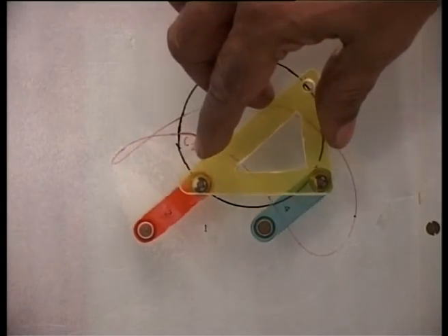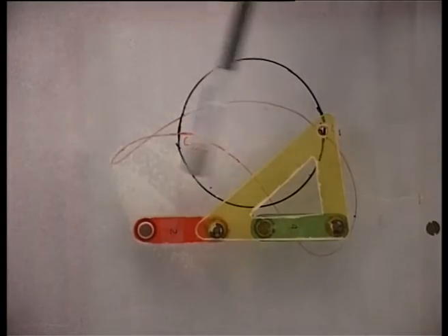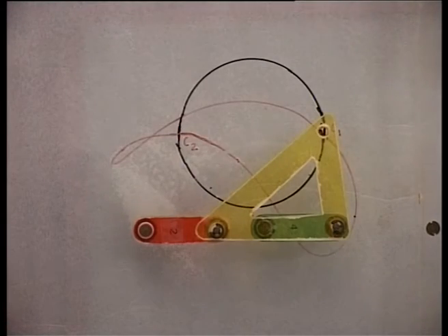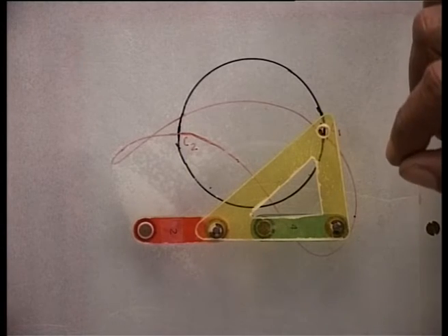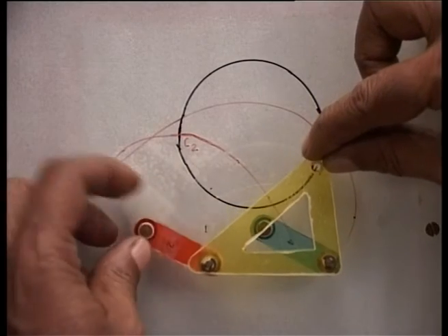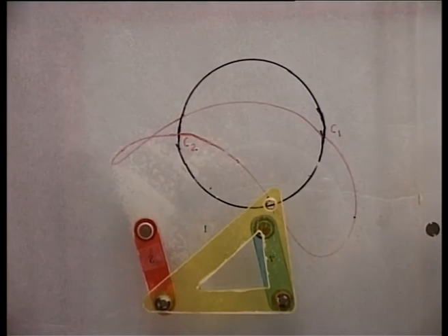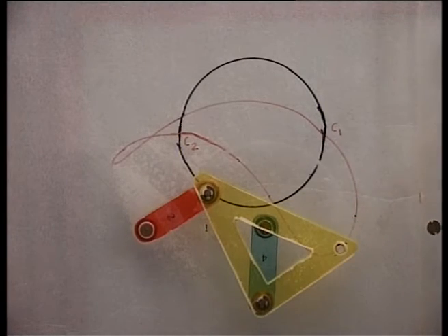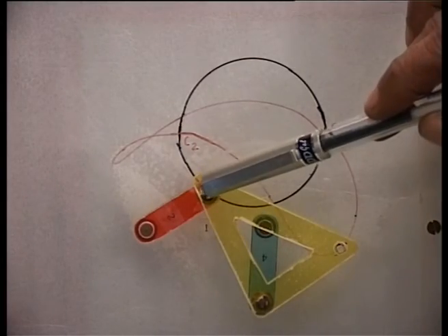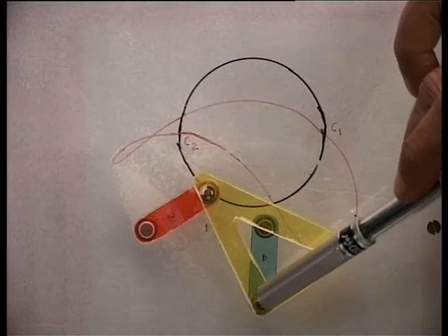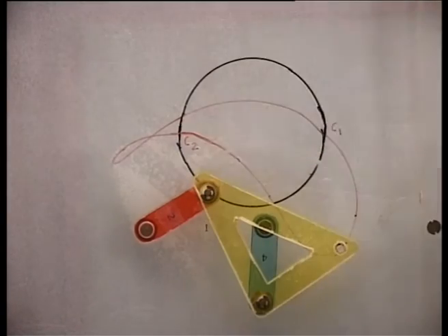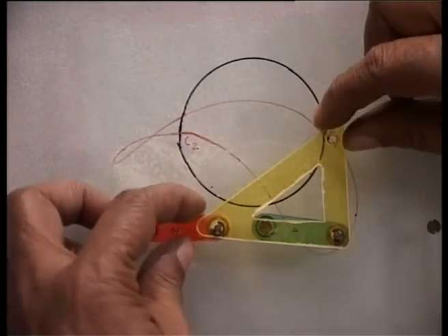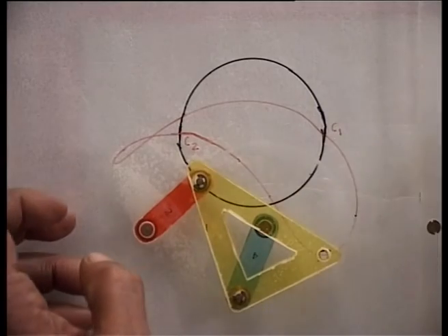As this parallelogram linkage moves, it is easy to see that there will be instants where all the four revolute pairs have become collinear. As a result, the linkage is passing through its uncertainty configuration, and from here non-unique movement is possible. If sufficient care is taken, we can maintain the parallelogram configuration. However, from this uncertainty configuration, it can also flip back to anti-parallelogram configuration, and it is no longer a parallelogram. The two opposite sides are equal, but it is in the crossed configuration. This is called anti-parallelogram. So, at this uncertainty configuration, the linkage becomes uncertain whether to maintain the parallelogram or to flip back into anti-parallelogram configuration.